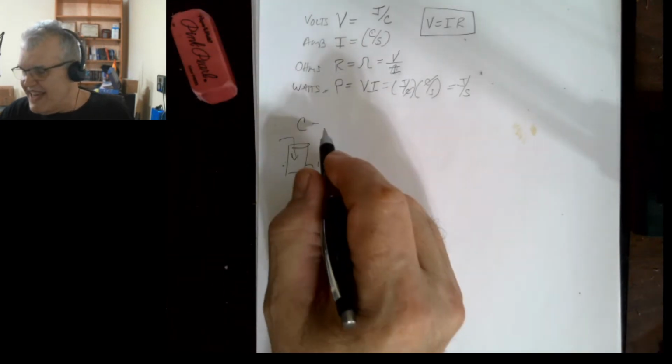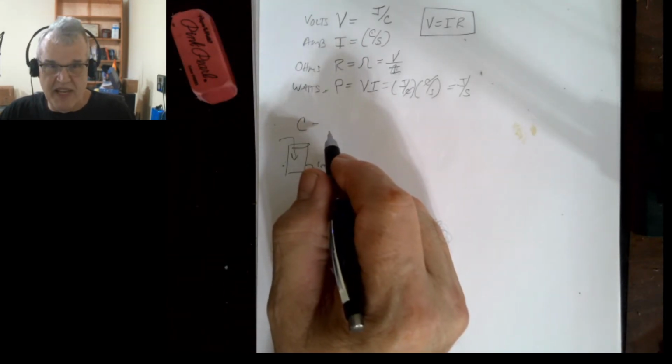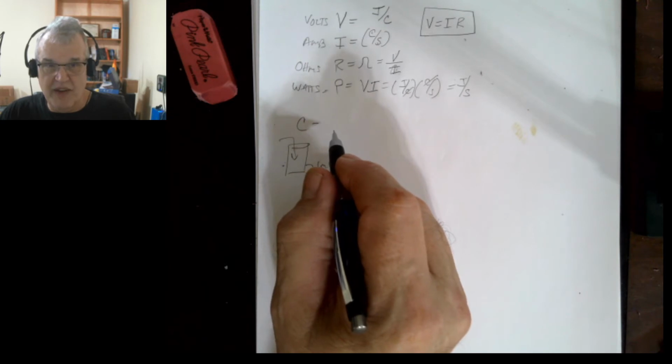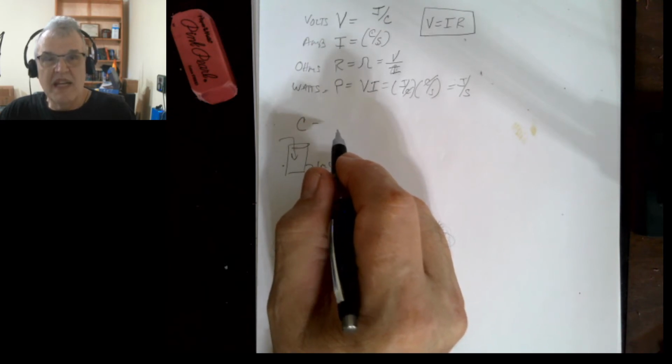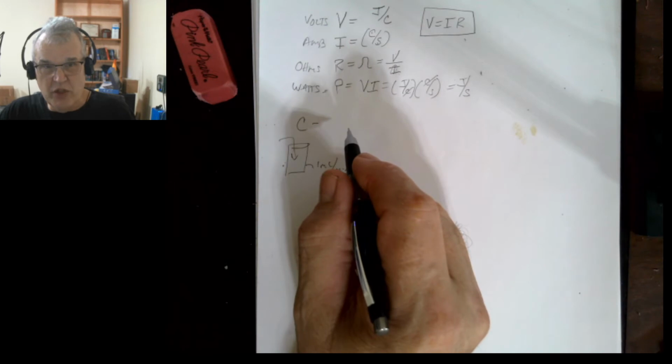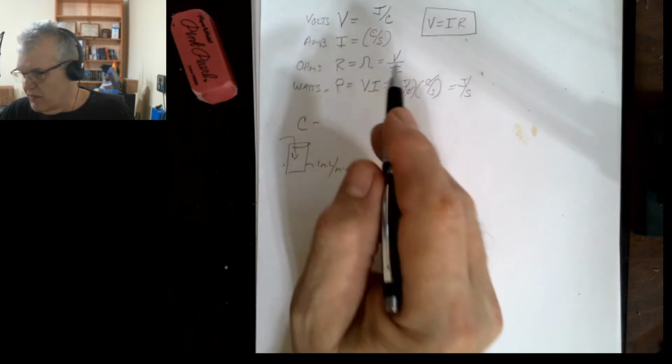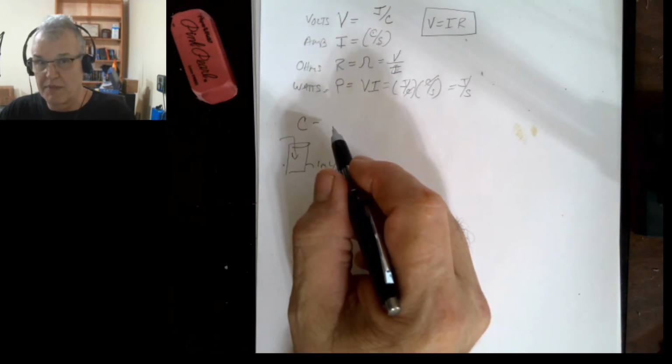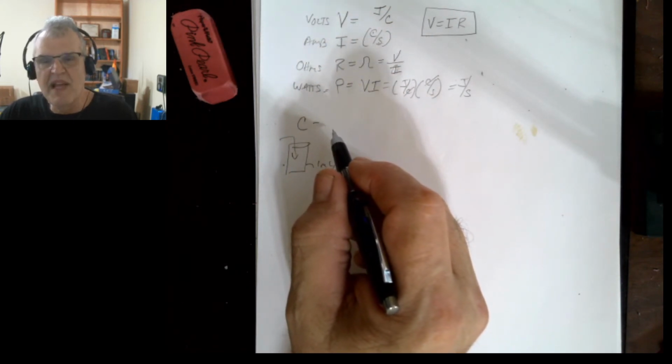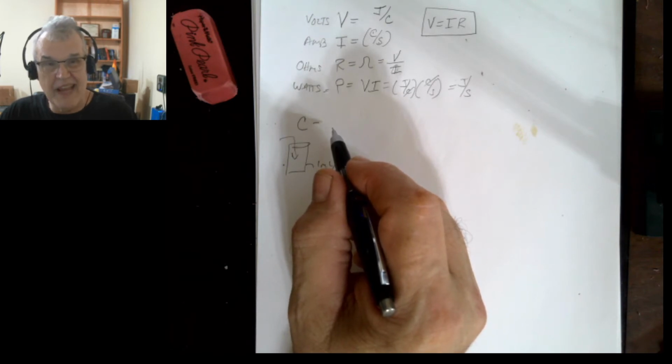So if we had a battery that has a capacity of 2.5 amp hours, then if we were to discharge it at 2.5 amps, a current flowing out of it at 2.5 amps, and remember amps is coulombs per second, we're doing 2.5 coulombs per second, then it would be able to give us that amperage coming out for 1 hour.